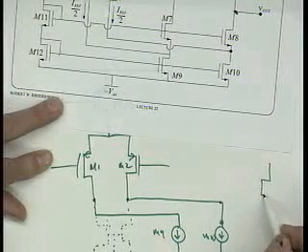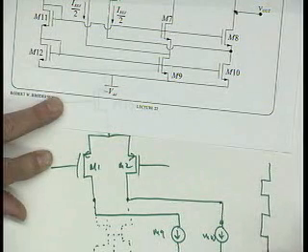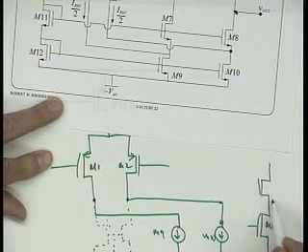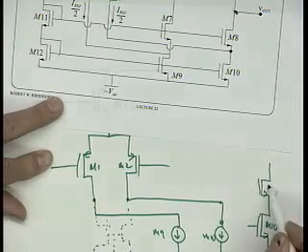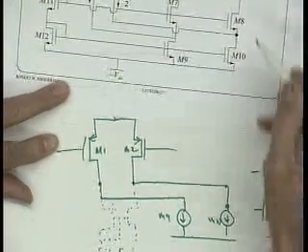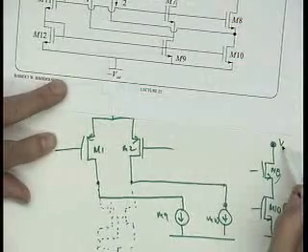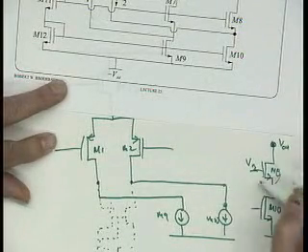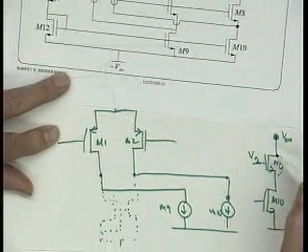See what's going on there? So let's say this is M8. This is M10 rather. So what's this guy here acting like, relative to this point right here? Here's where V out is being taken, above M8, right? So here's V out. So what's M8? This is a V bias. So what is M8? It's a common gate.